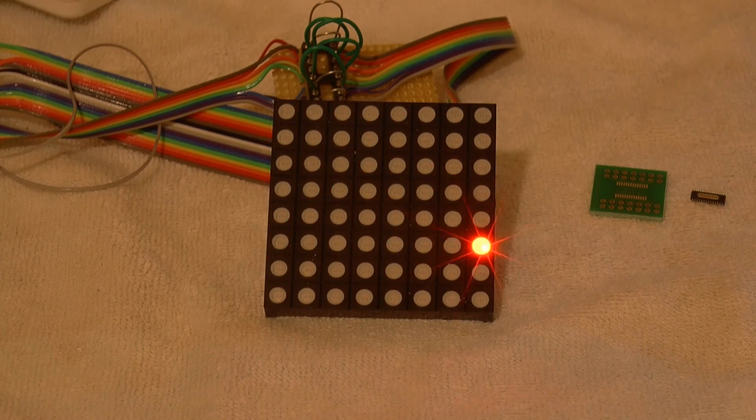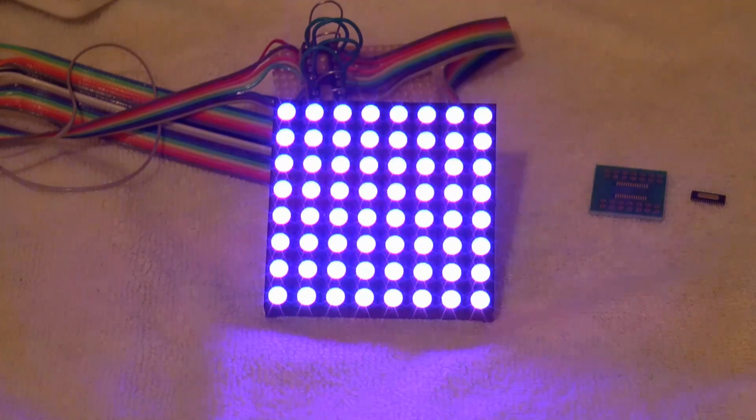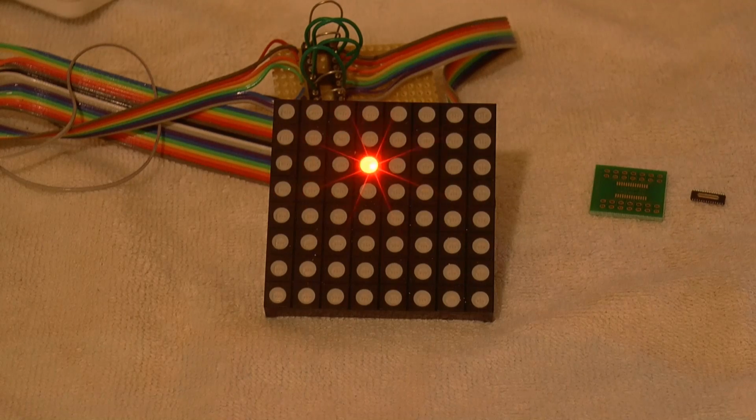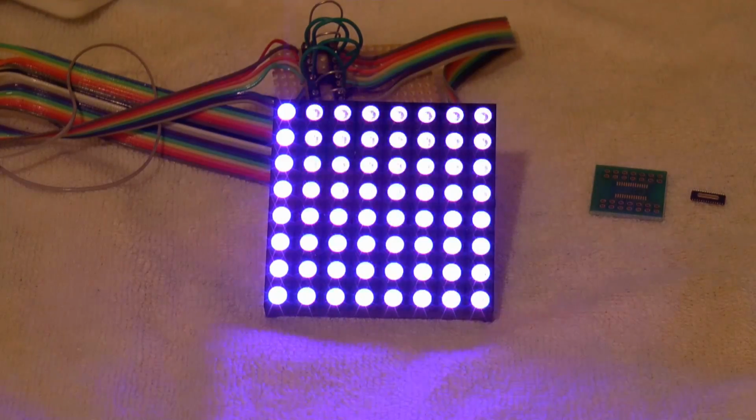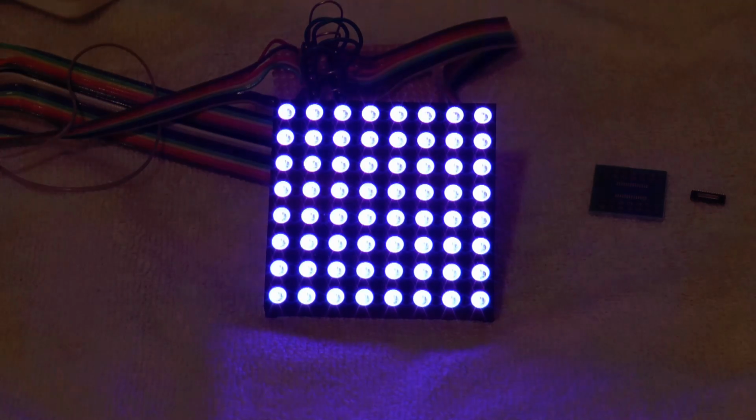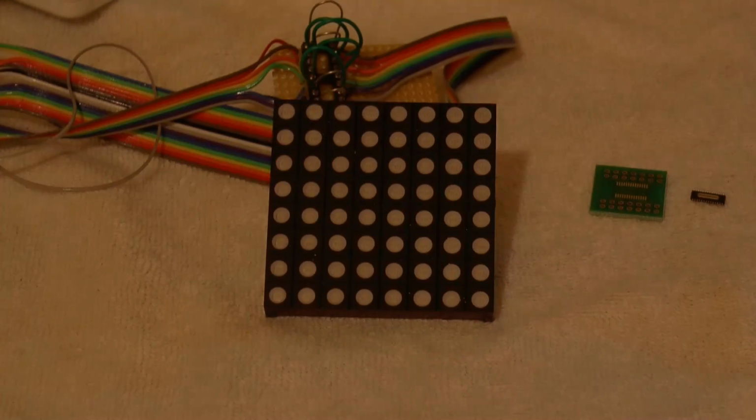So I've just recently got this LED matrix, 64 LEDs, actually red, green and blue. I've not used the green. I've got it wired up to a Texas Instruments 16 channel LED driver with dot correction and grayscale PWM. But for simplicity I'm just using the dot correction.